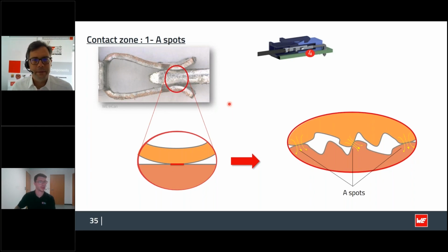Okay, regarding the time, last question, Florian: is galvanic corrosion only a concern when dissimilar metals are in physical contact? Yep, to make it short, that's an aspect. Also, what you need to take into consideration is the environment. If you have an environment where some moisture might occur, or a moist environment in combination with a higher current, galvanic corrosion might be more critical.